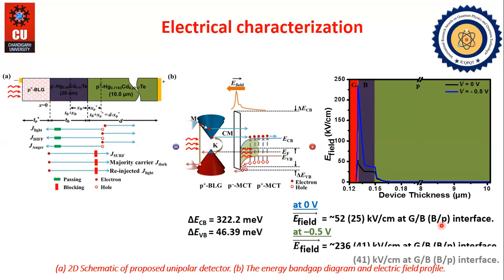So under the illumination, the photo-induced holes in the active layer flow to the anode across the very small valence band offset, whereas photo-induced electrons are quickly separated by the cathode under the high reverse bias condition, thus causing the flow of net photocurrent density into the external circuits.